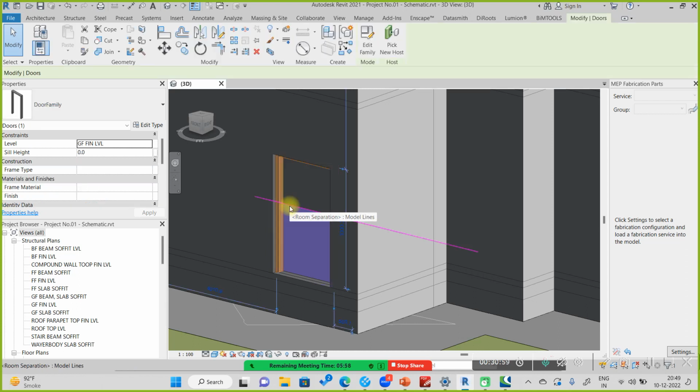Okay, now you can continue your work to complete the door family with the frame, with the panel, with the accessories. Okay, over the weekend, right? You can choose any kind of door you want to make, but then it should be parametric. I just need the two parameters here, the width and the height of the door. That's it. If I change that, I should be able to get all the nested families parameters updated. Getting it?